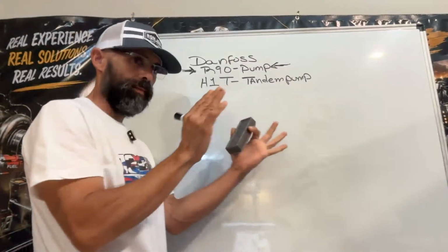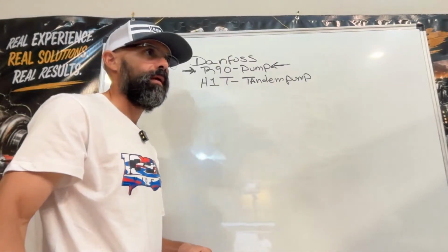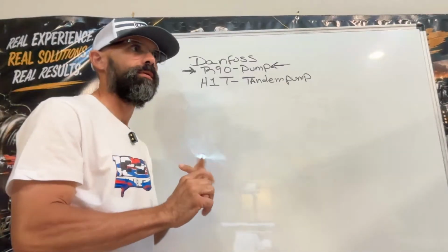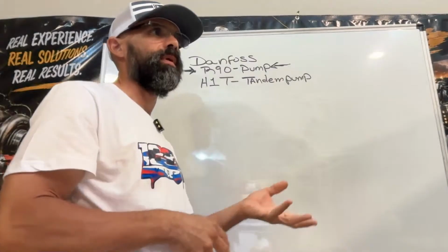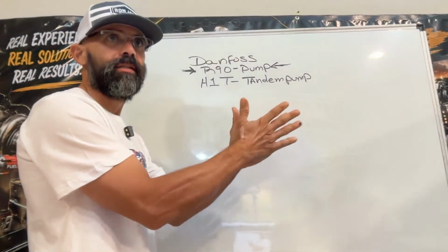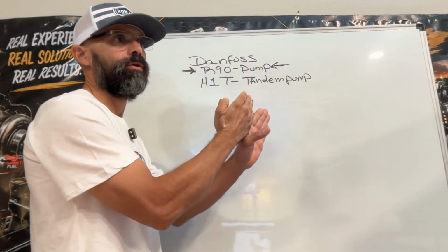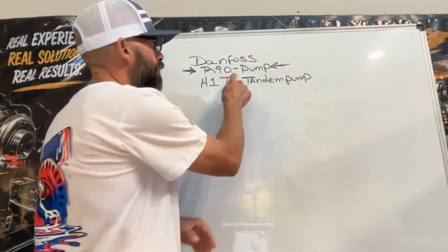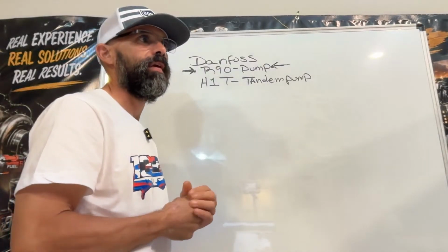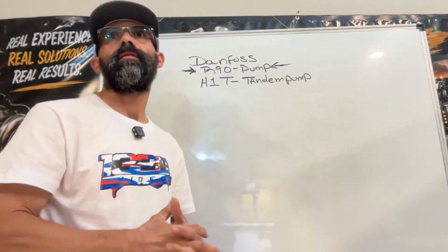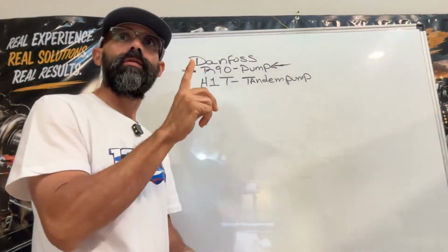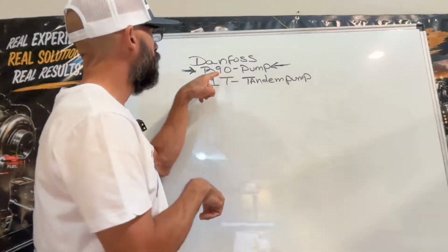So on the pump, you're going to have your hydrostatic system with the swash plate, the slippers, the valve plate, the rotating group, and on the back of the pump you're going to have your charge pump, right? But every pump for the R90, 75, and 95 has its own relief valve for the charge pressure. That way you can either increase or decrease the charge pressure on the pump.